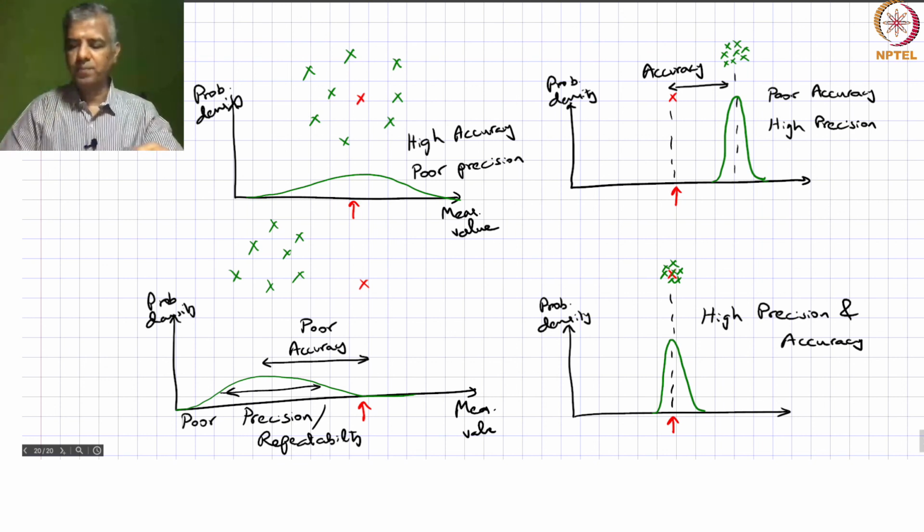this is poor accuracy, all right. So it basically says, okay, I'm expecting 100 ppm and it shows me 120 ppm. But if it is scaled, if it is 50 ppm, it's actually showing 60 ppm, right?